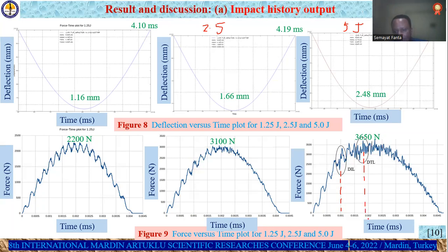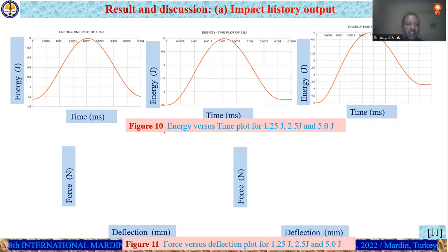That is the time at which it was achieved. It is less than 2 millisecond, about 1.8 millisecond, at which the damage threshold load is achieved. Then after that the structure comes back to the zero position, which implies the elastic response of the material. Okay, and then another is the energy-time curves. This energy-time curve shows the amount of energy dissipated.